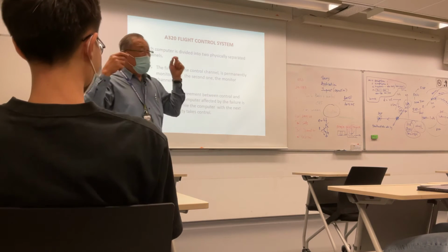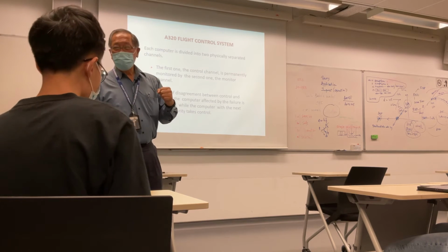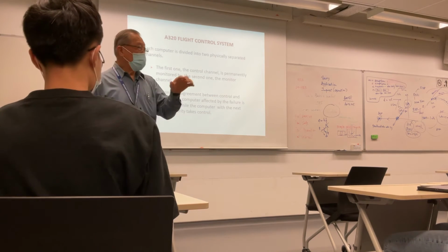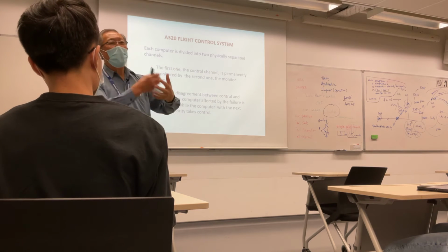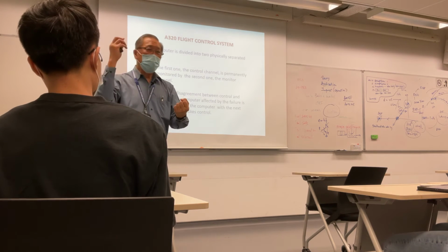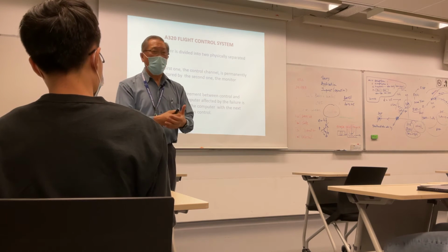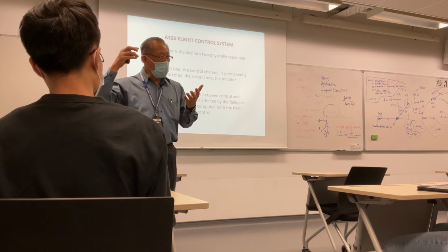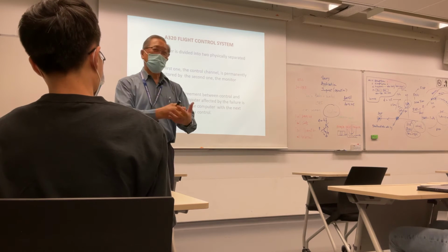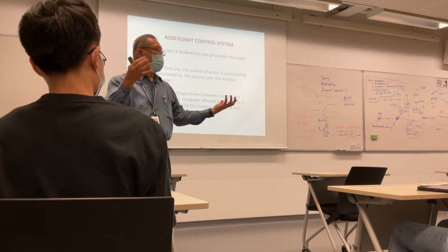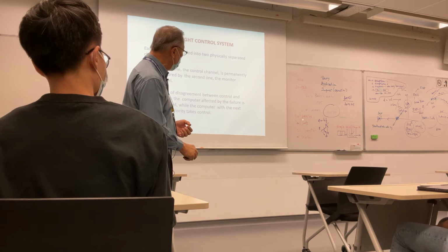Whereas on the bus, the pneumatic brake is actually fail safe. They use the pneumatic pressure to lift the pad off. So when the pneumatic fails, it's always locked. The brake is on all the time. They use the air pressure to lift the brake and move the bus. So that is fail safe. This is a simple illustration. All aircraft systems have to go through fail safe design.